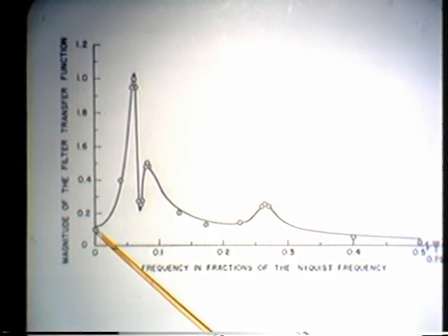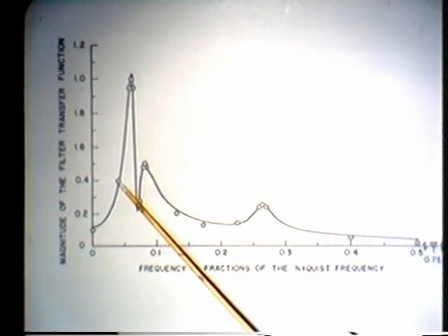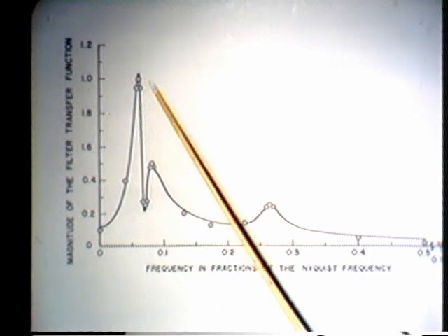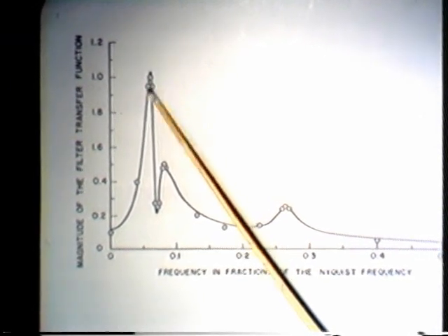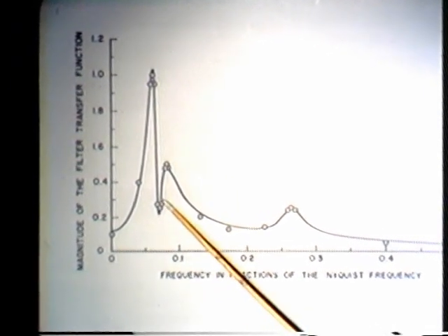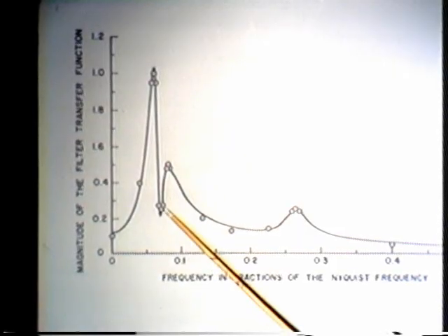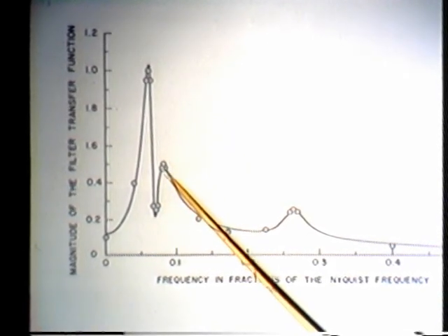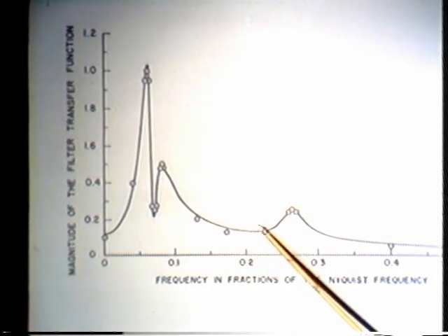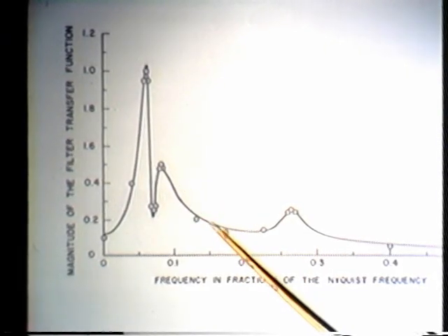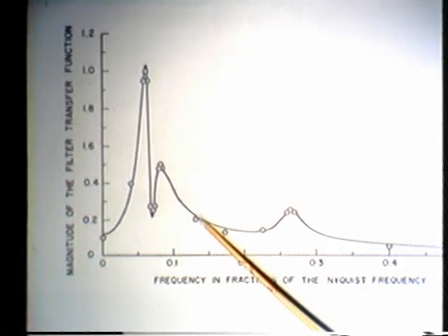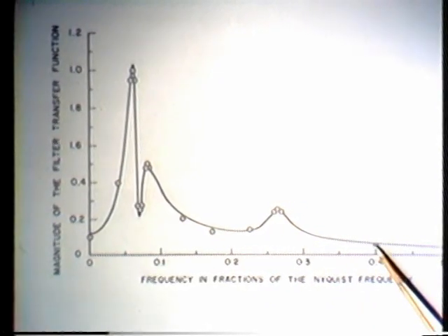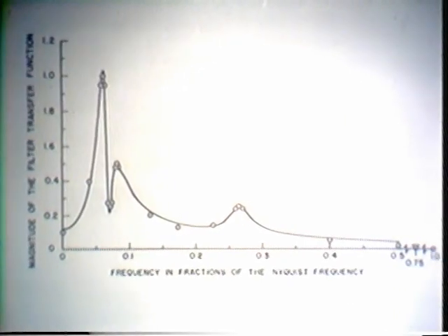The frequency response was specified to have that value there, one here to get us heading toward the resonance, 3 points at the peak of the resonance there, 3 points to force the frequency response back down again, another 3 to bring it back up for the second resonance, a few points distributed along here to provide a general characteristic to tend toward the next resonance, 3 points at this resonance, and then a few points to have the frequency response taper off.